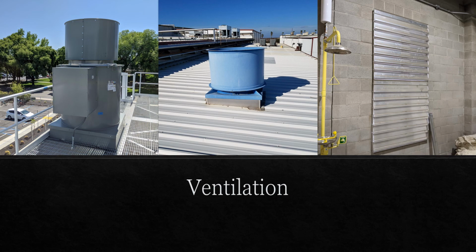Other ventilation system requirements include the system must be automatically activated if the ammonia concentration reaches 1,000 parts per million, fan blades must be non-sparking, fan motors in the airstream must be totally enclosed, a monitored location must be notified if the ventilation system fails, makeup air must prevent short-circuiting, be uncontaminated, and serve only the machinery room, and where utilized, motorized louvers must fail open.